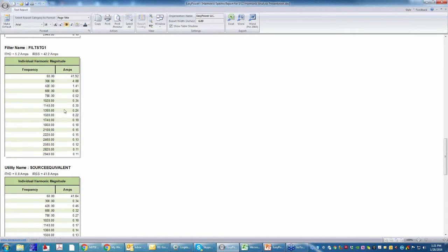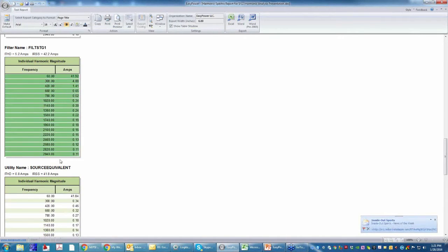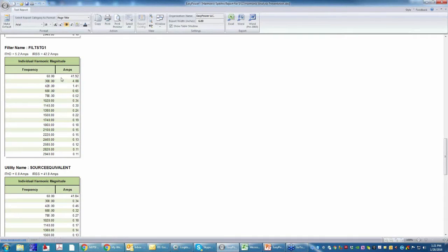And being a manufacturer of this, we often see specifications like that, where somebody has taken the output of a harmonic analysis program and sent it to us and said, design us a filter for that. The reality of the situation is this filter should be designed such that it contains at least roughly a 20% overcurrent factor in the fundamental. At Northeast Power Systems, we actually will design the fundamental reactor current rating at 1.5 times its nominal current rating. And then at minimum, the tuned frequency harmonic current should typically be at least 50% of the fundamental current.